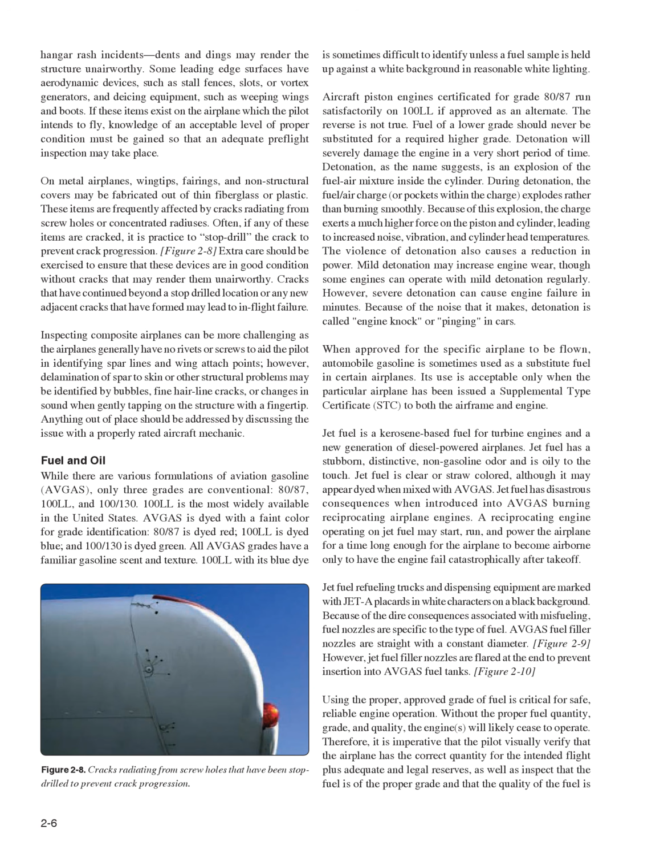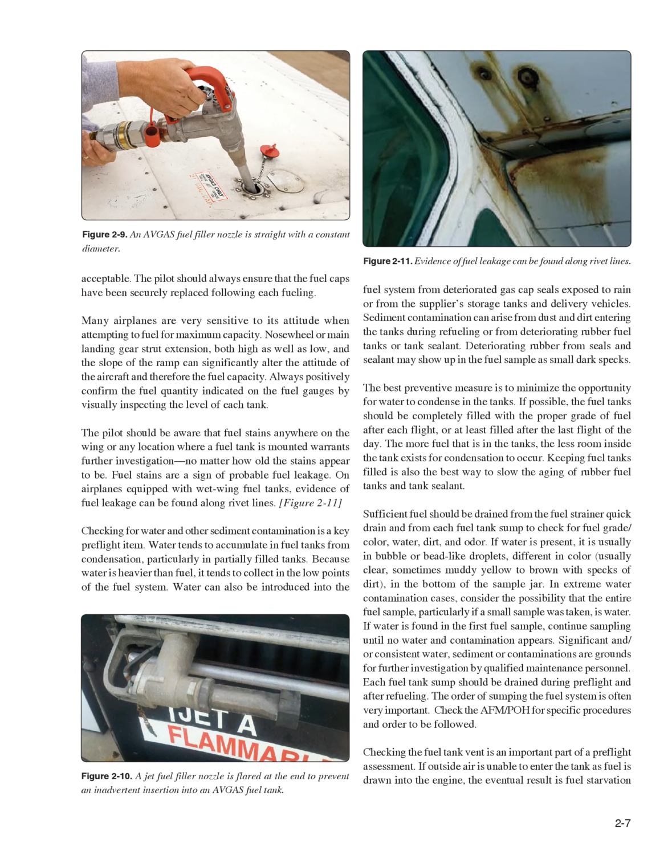Therefore, it is imperative that the pilot visually verify that the airplane has the correct quantity for the intended flight plus adequate and legal reserves, as well as inspect that the fuel is of the proper grade and that the quality of the fuel is acceptable. The pilot should always ensure that the fuel caps have been securely replaced following each fueling.